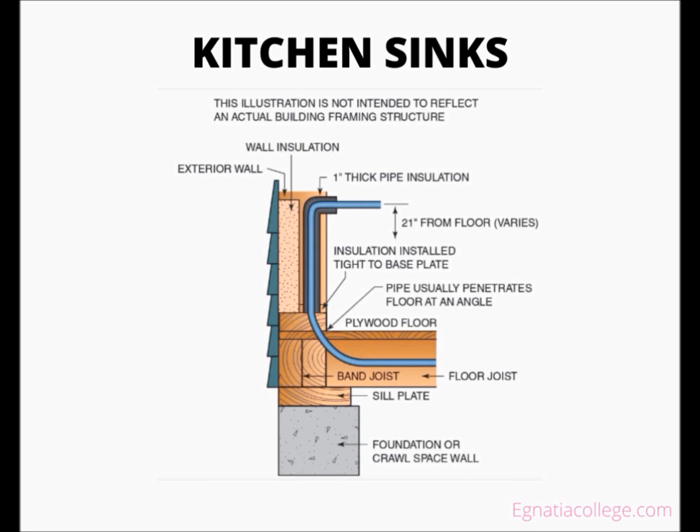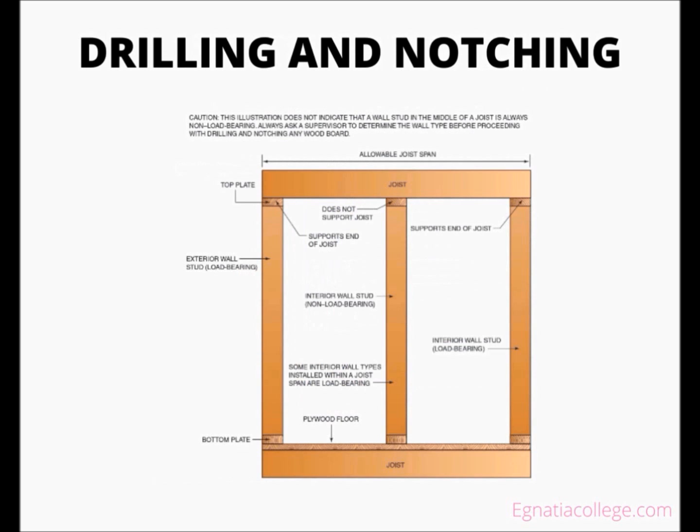Floor penetrations can be used to route the water piping vertically into the cabinet if there is a crawl space or basement below the sink cabinet. The insulation requirements of exterior walls vary in different regions, but most plumbing codes dictate that the water piping must be installed on the interior side of the wall insulation. At least 1 inch of insulation must be installed over the pipe according to most plumbing codes.